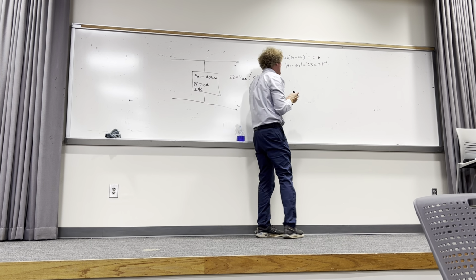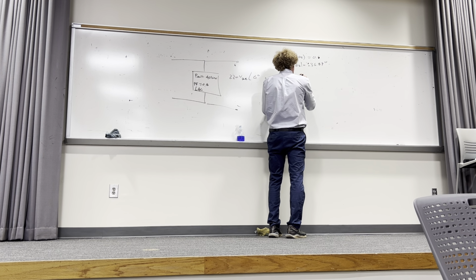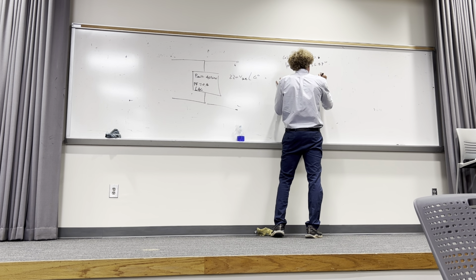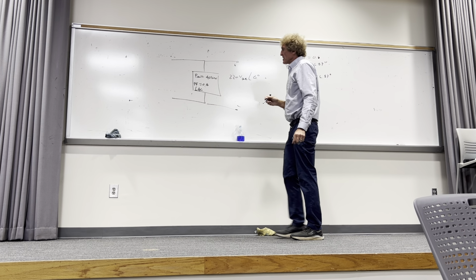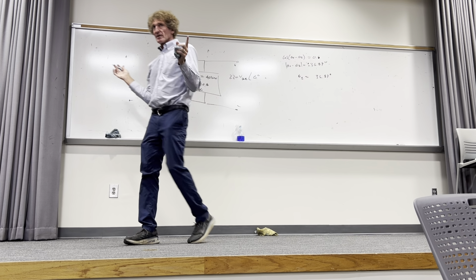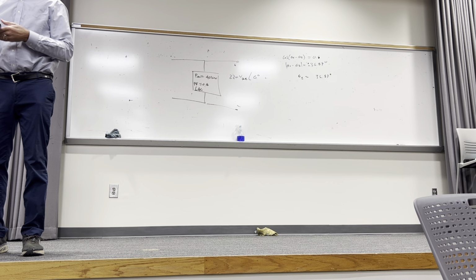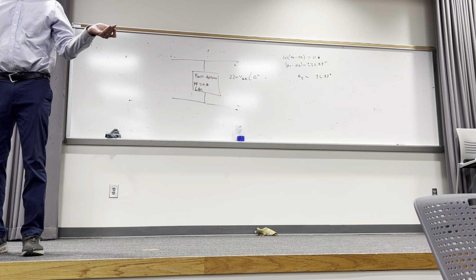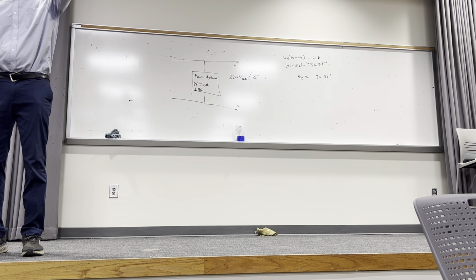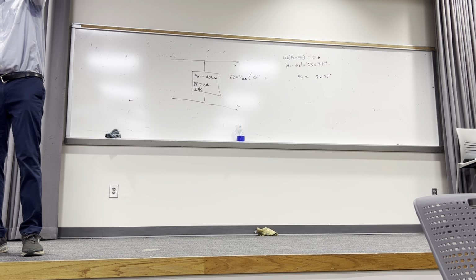So that means theta I, or the angle associated with the current, is plus or minus 36.87 degrees, right? How do we get the sign of that? How do you know the sign? Or it is negative, right? The current angle is behind the voltage angle. How many understand that? Make sure you do. Far back, guys.